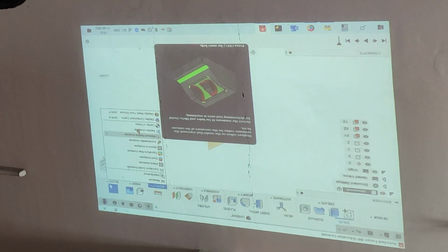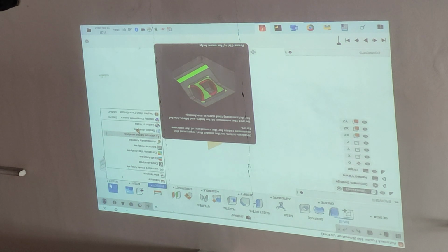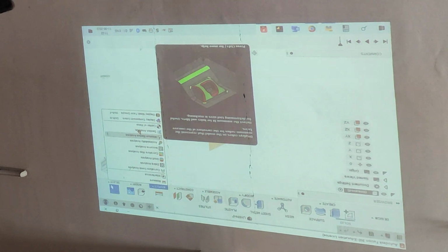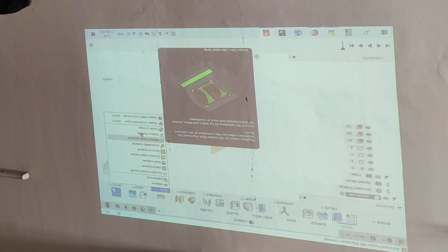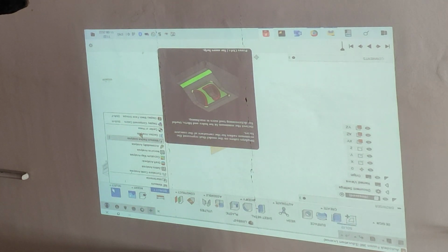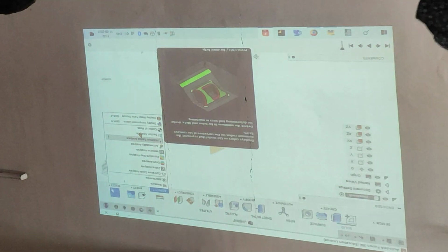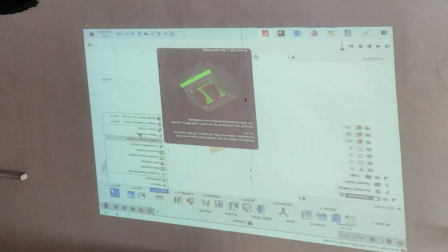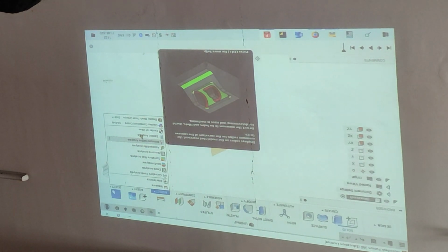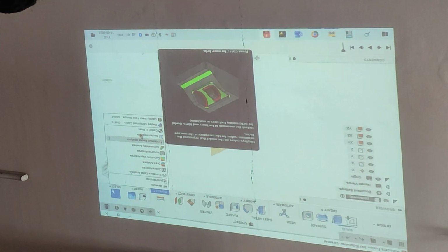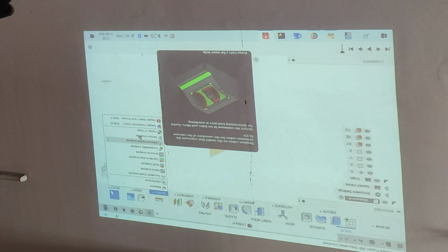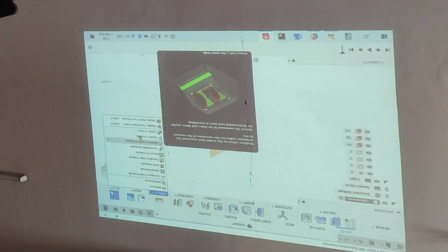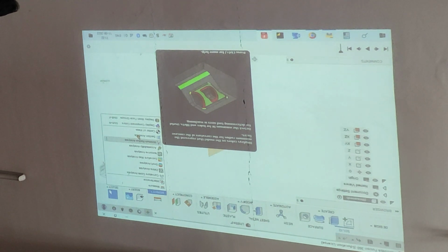Okay, so these are DFM, design for manufacturing. Then DFA, design for assembly. For example, if you are making that network box, and I make a sheet metal out of that and fold it, the screwing areas inside, after putting that, how will I access them? If I fold it and the screwing areas are covered, then the operator cannot put the screwdriver inside. So it's completely locked down. So these are the things you have to consider when you do DFA, design for assembly.